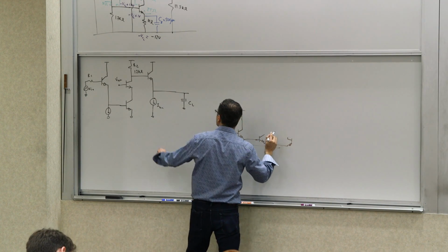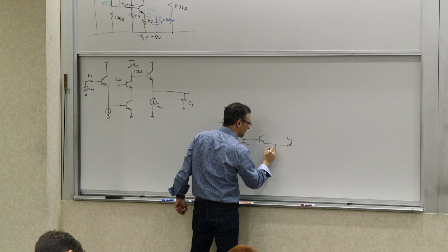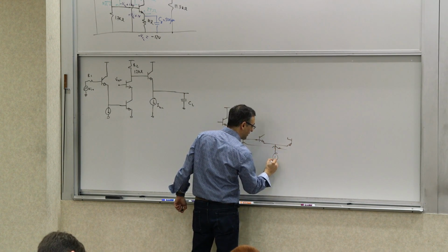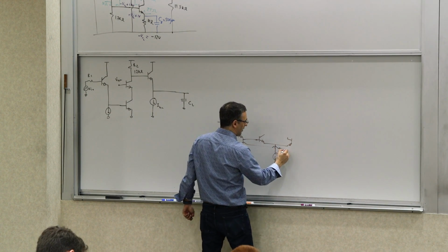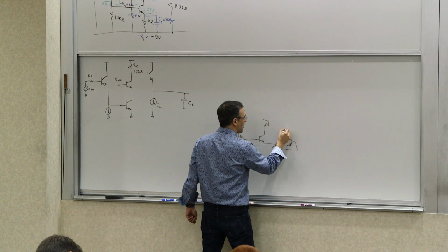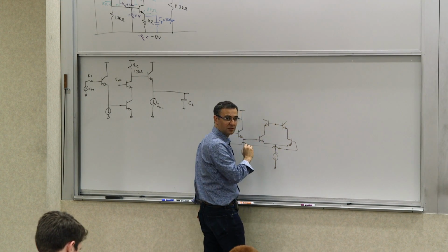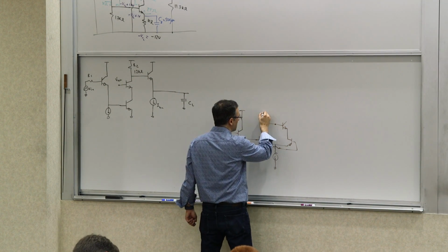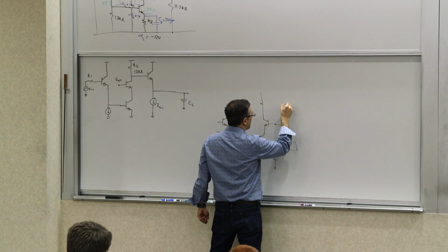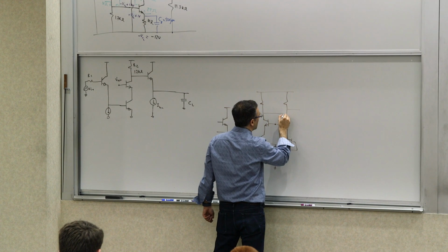So these 2 are a representation of that guy. You need another current source here. This goes to the input. You need to make it into a cascade. You make that differential. We need to generate this bias current, bias voltage. We can do it in various ways. You can have the resistive loads.